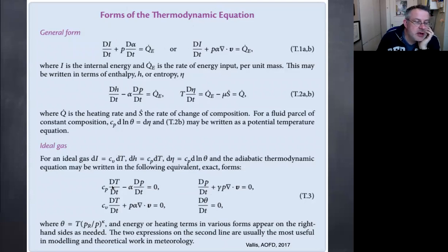So here is the internal energy equation written in terms of the temperature. And we have a pressure part. Oh, sorry, no, we have switched the order, which is a little confusing. Sorry, this is the one that results from the enthalpy equation. We get a temperature change, we get a pressure change. We have specific heat there. We have the specific volume here.